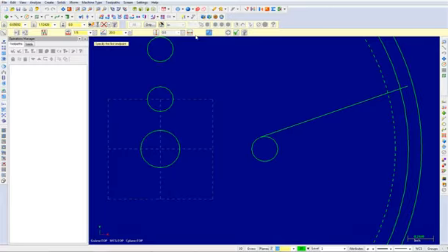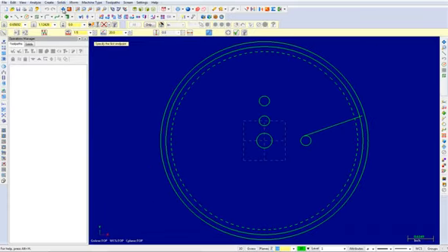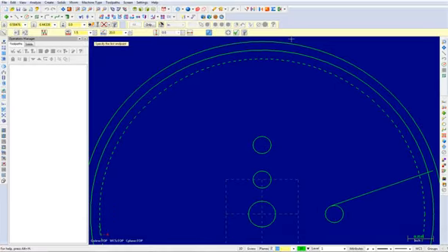Select the fit icon to view the whole geometry. Again, choose the zoom window button. This time, zoom in on the following area. Select the following arc as shown. Again, remember that you are not selecting any endpoints, midpoints, or quadrants from the arc. If you select one of these points, Mastercam snaps to the points and disregards the tangent option. Complete the following action.